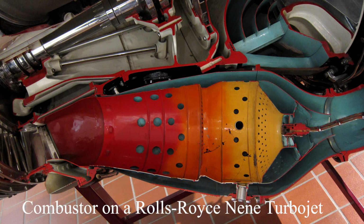As turbine blades continue to grow more advanced and are able to withstand higher temperatures, the combustors are being designed to burn at higher temperatures, and the parts of the combustor need to be designed to withstand those higher temperatures. The combustor should be capable of relighting at high altitude in the event of an engine flameout. There must be a uniform exit temperature profile.